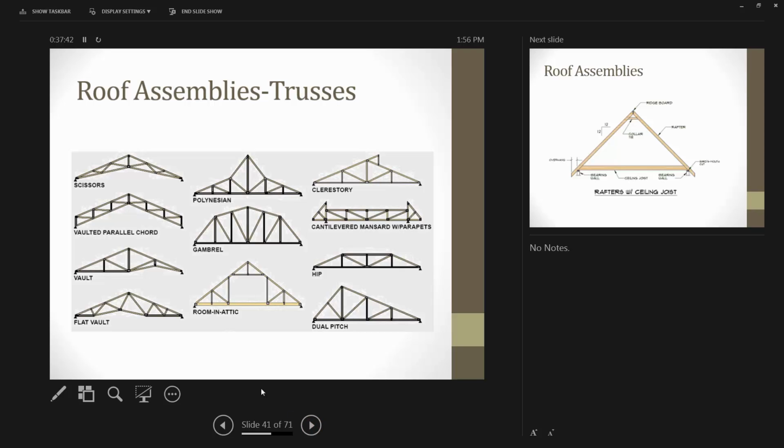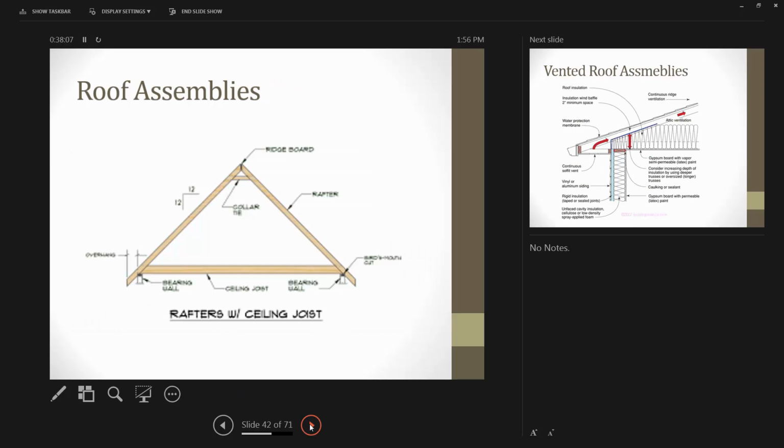And the very end of a truss, if you look at some of these like the scissors truss, the very end of the truss comes to a point, and that point usually ends up at the end of the wall. And so if we're trying to get a lot of insulation in our ceiling, but we come to a point at the end of the wall, we've all of a sudden decreased the ability to get that insulation in there. So we'll talk about raised heel trusses and strategies on that in our envelope, and I can show you, I think, in the next slide.